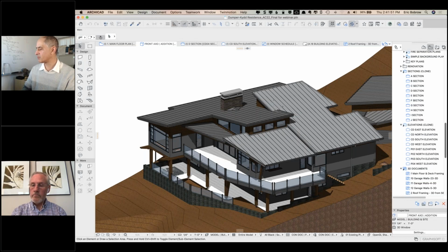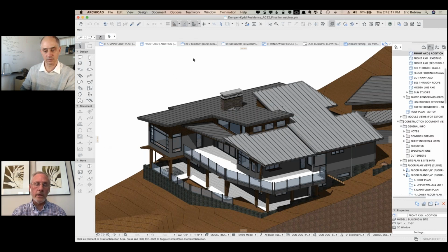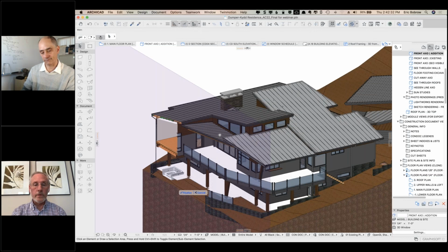Right. Okay. So Tom Marcunas clarified about the drainage plan. He was asking about the airspace between standing seam metal roof and the substrate. There's standing seam. Yeah, there was cross purlins on there. I think at the end of the day, we may have done spray foam insulation into the vaulted sections of this house because it's a simpler detail, and it's becoming a lot more common here, and then you don't need an airspace. It forms the vapor barrier and solves that problem. So I think it will be building code at some point in Canada.